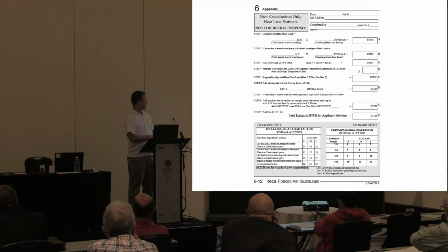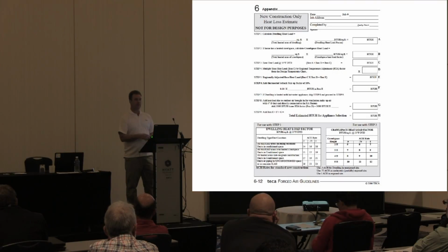And then we add the heat of the outdoor air, which times the regional temperature adjustment, so it's 3,000 BTUs. And then we add it up and we're done. And we have our base heat loss. This one's probably within 15% of the actual room by room.